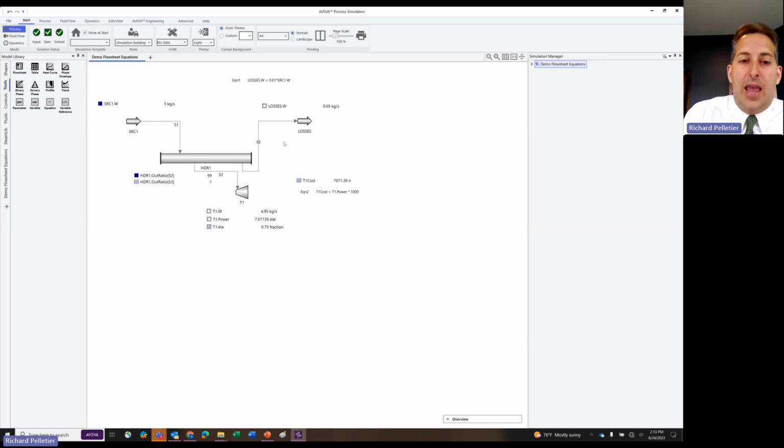They're all being calculated, and they're being calculated at this point based on a cost, right? So, maybe I know that I need to make this $5,000 or less. Right? So I can type in 5,000, and I can see, all right, what does that relate to in terms of a power, in terms of a required flow rate coming into my header, right? So I have the flexibility here, just like I did with any other equations and variables, to spec this and work backwards through the relationships I've added via the equations to change the way that I work with and manipulate the file.